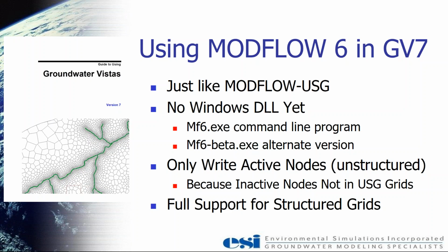Well, I shouldn't say that. You have to do that if you have any inactive cells, because as I mentioned earlier, MODFLOW 6 does not have the concept of an inactive cell in an unstructured grid. So that gets turned on automatically when you switch to MODFLOW 6.